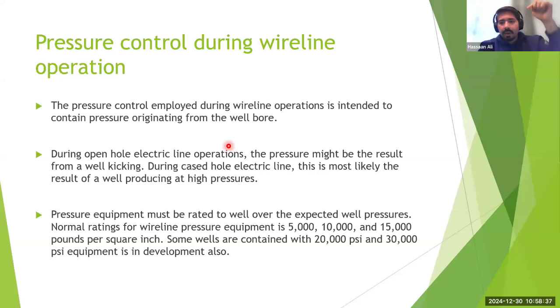And you have just one wireline cable that is being run from the surface to the bottom, right? So imagine the weight of those tools on that cable and the entire length of the cable, right? So the combined weight of the tools should be within the safe working load of the cable.